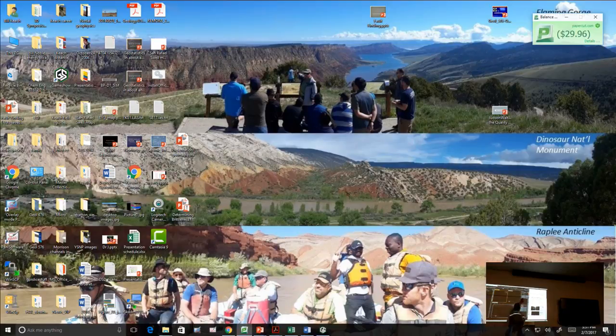Under interpretation sets, or I sets, they call it in the documentation. It's a way to say, whenever I come into this project, I'm always going to work with 2D seismic, 3D seismic, and a certain set of wells. The exercise at the end of this chapter is to build your own I set. So we're going to use some existing ones right now to bring some data in. If you don't have an I set, you can still bring in data individually, one chunk at a time, and then save it as an I set. That'll be your exercise. So we're just going to choose an I set right now.